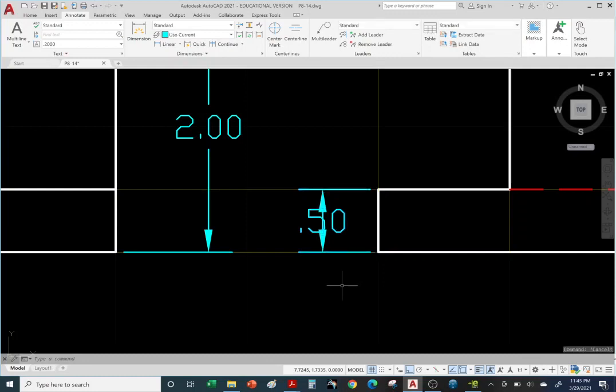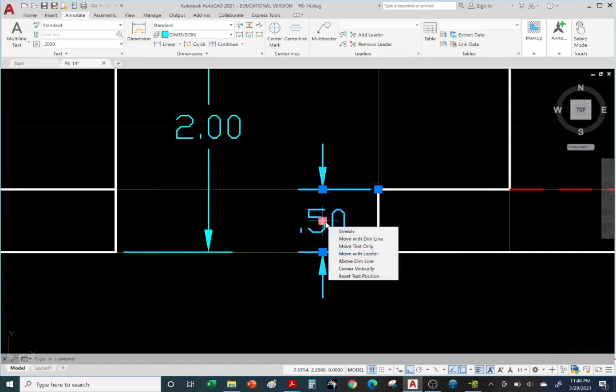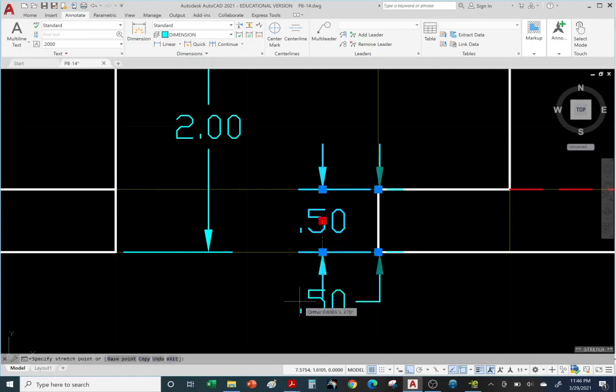it just doesn't look right. So you don't want to place a piece of furniture in your home facing in the wrong direction or crowding itself. So, hey, we need to do something to make it look nice. So we can just click on the dimension. Now we see the blue grips, hover over them and flip the arrow. Okay, another option, if you still think it looks too crowded, you can leave it the way it is, or you have the option to actually take the text out. So I'm going to hover over the grip over the text, and I can take it outward, as you can see.